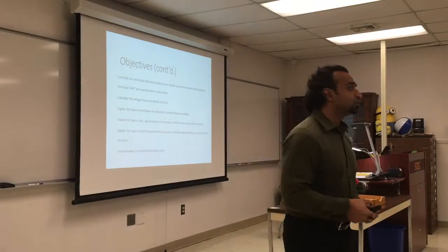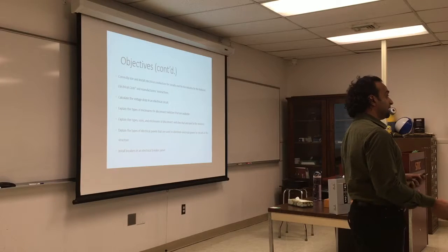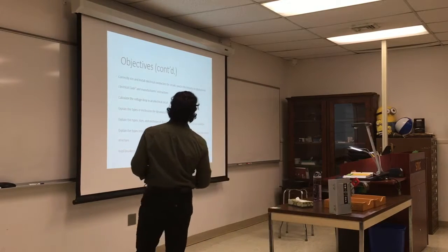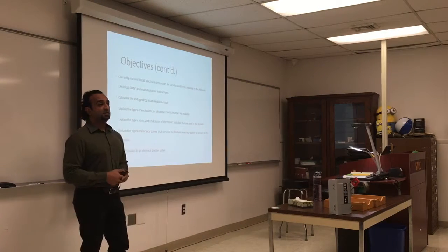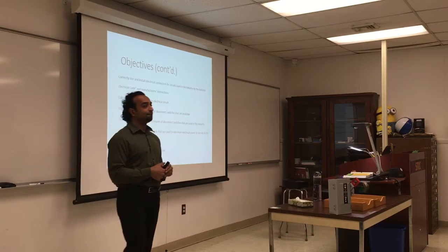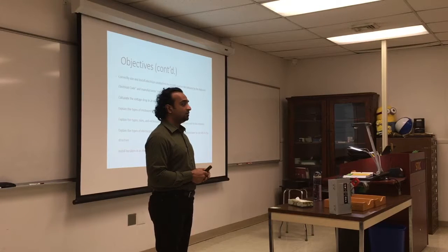By code, you're not supposed to have any exposed wires. Everything has to be in a conduit for protection and also so it will not be pulled and disconnected. So that's something also we'll talk about. And especially if you put the equipment outside. What equipment is usually placed outside? So that way they're not inside the house. No, but which one?